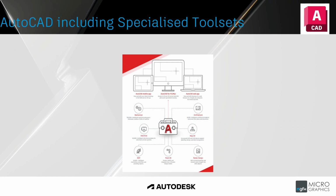So that was just a look at the major differences between AutoCAD and AutoCAD LT. You see there aren't many, but I think the data extraction, for me, is probably the biggest thing that warrants going with the full AutoCAD instead of AutoCAD LT, because of that count. Being able to count and put a bill of materials or a schedule onto your drawing and get an exact count is a very, very valuable tool. Yes, you can create attributes, which is part of the data extraction, in AutoCAD LT, but essentially you can't get that count right at the end.